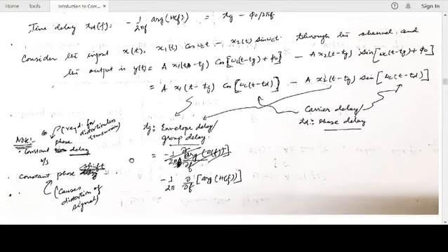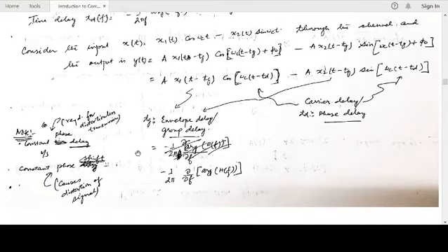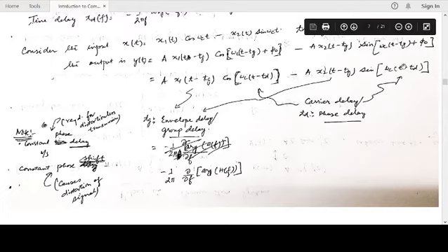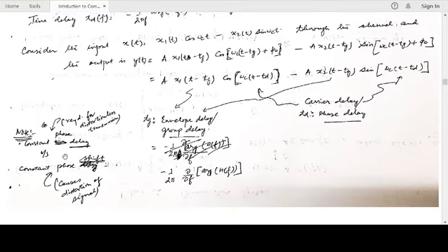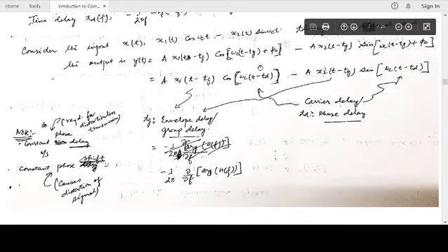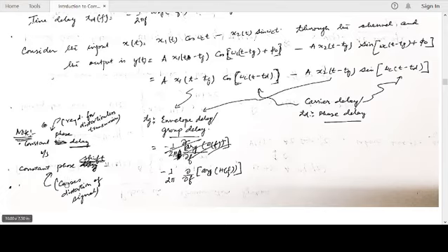Okay. So now we will try to understand the significance of them by an example, but before that we'll try to see that often we confuse between something known as phase delay and phase shift. Constant phase delay means the carrier is delayed by a constant amount, that is desired, as we said. It is required for distortionless transmission. Constant phase shift means that the carrier has a constant phase shift of phi naught, let's say, whatever it is. So it causes distortion of the signal. We'll see what that means.